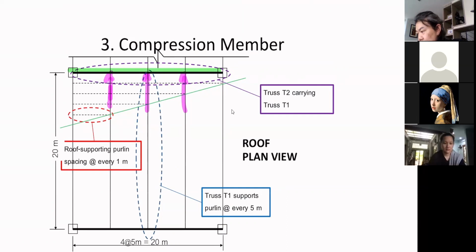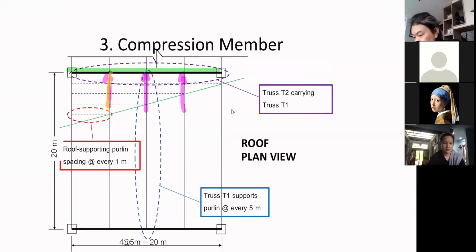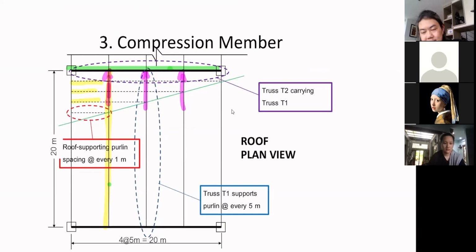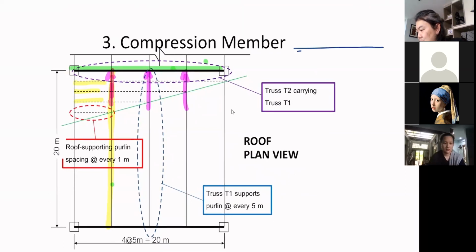You see, this is the typical truss in this line where it supports purlin. So this is the purlin coming in, and this truss will be fine because it has purlins to help as a brace. But in turn, the green truss here is built to support this yellow truss. So the yellow truss itself becomes a brace point of the green truss. So when you look at this green truss, let's say it's something that looks like this.